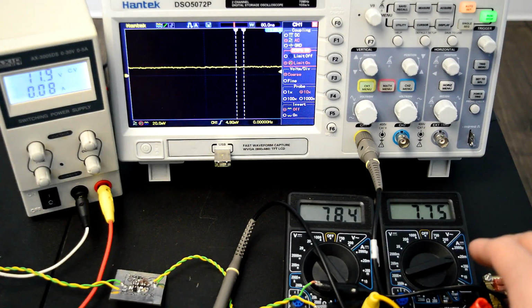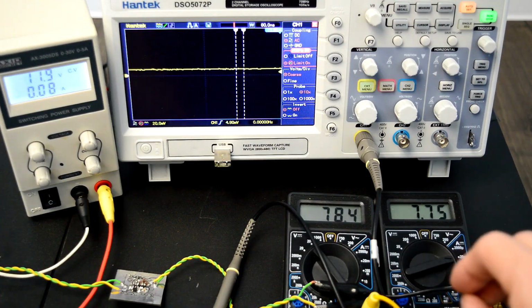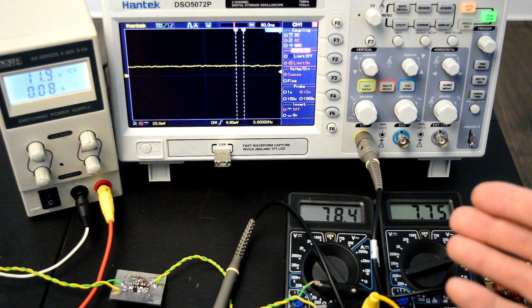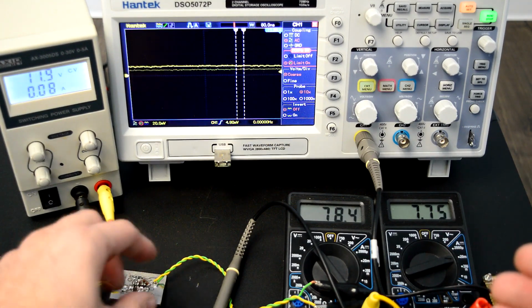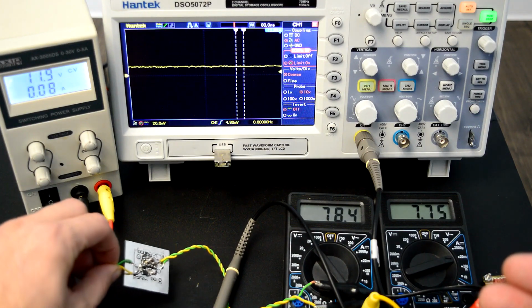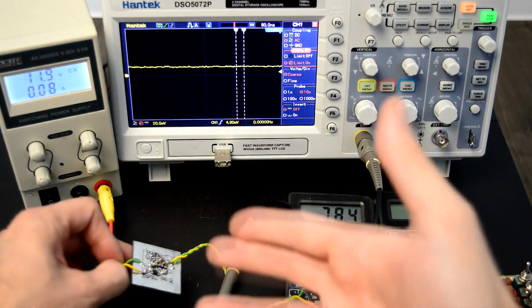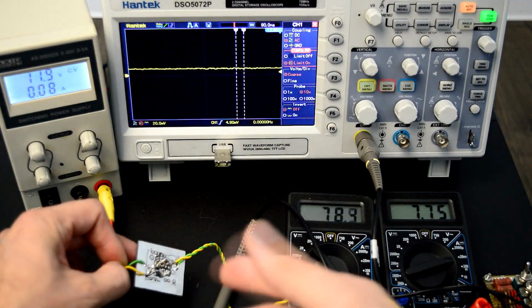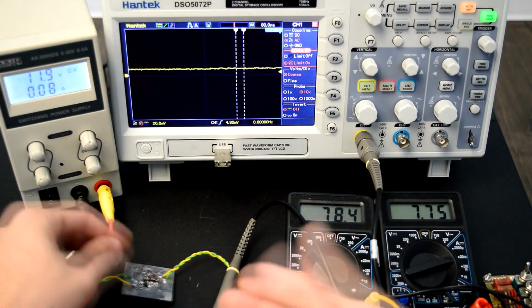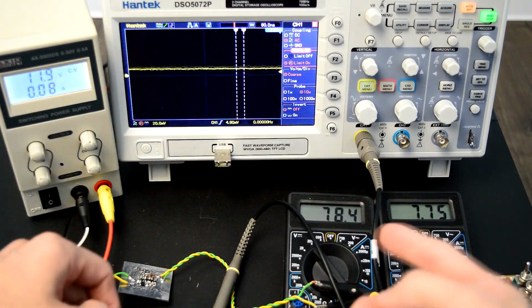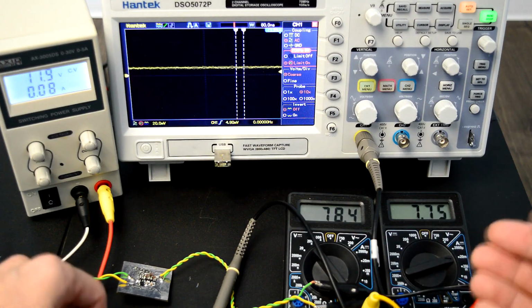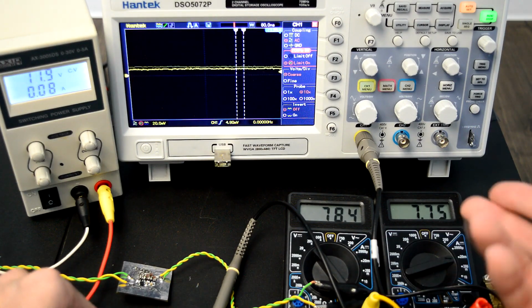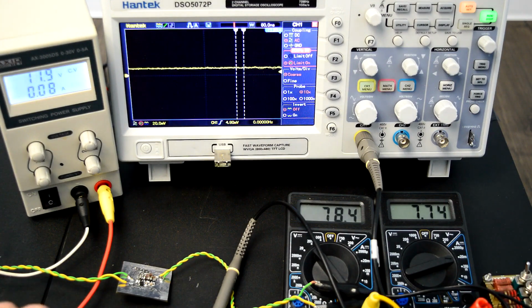Hello and welcome back. What I want to talk to you about today is switch mode power supplies and the noise they generate. For that I've got this little supply here which I've been working on lately. Basically this is a booster supply that has a voltage tripler stage on top of it. It's taking 12 volts and generating about 78, and right now the load is set so that there's 7 milliamps, well, almost 8, coming out of it.